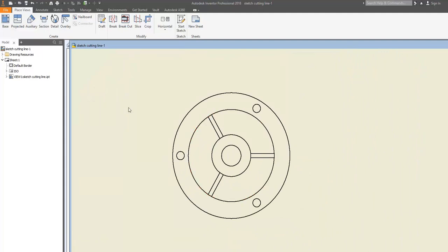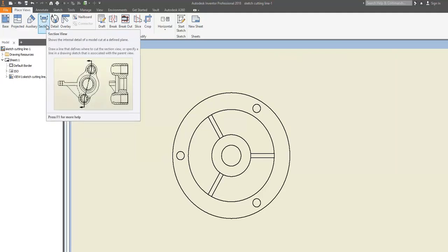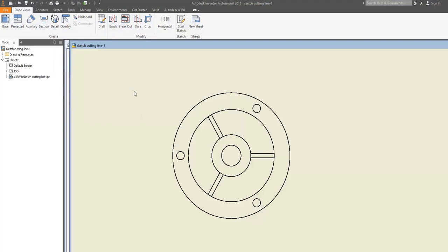Yes, sectioning process. But normally, clicking on the sectional view creation process icon, we can have the sectional view using a cutting plane with flat portions. But here for this revolved body, the cutting plane is to be the one with cylindrical segments. To be able to use such a cutting plane, in sketch mode, the edge of the plane is to be drafted in the method. Okay, then, indicate the view first. This is a trick. Bring the cursor to the vicinity of the view and then make a click.